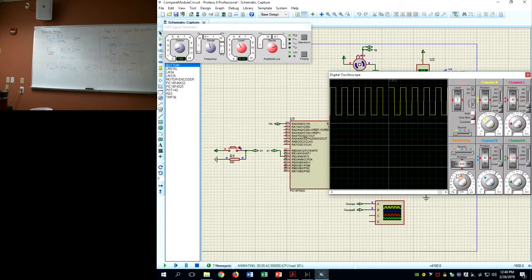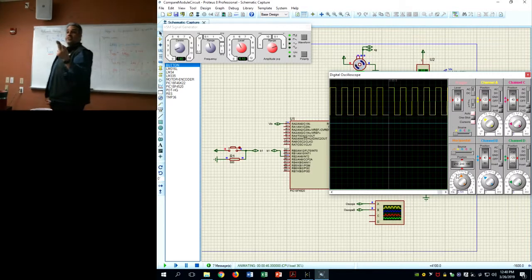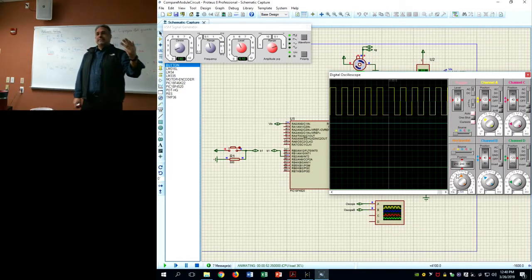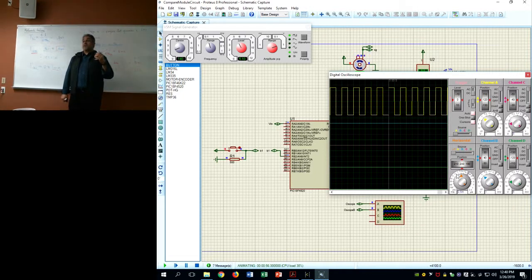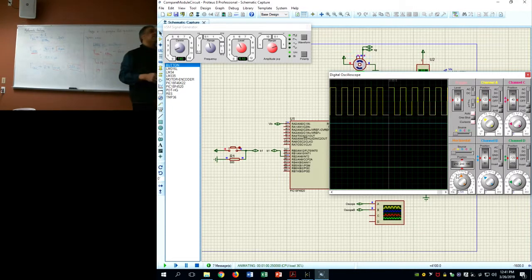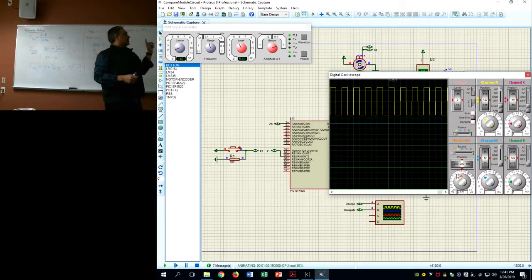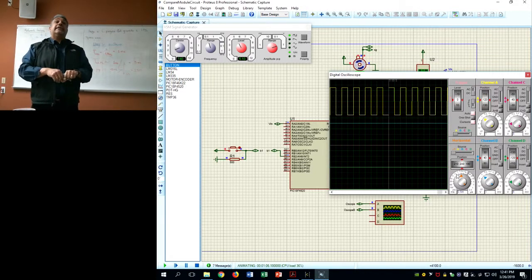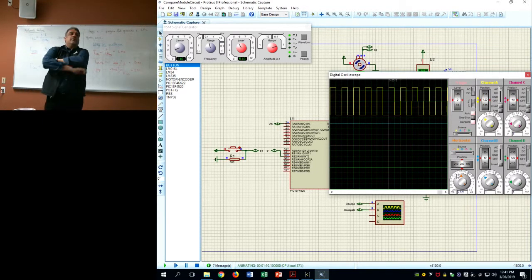You can do this for all kinds of applications. LED fading, you can do this for sound generation, beat generation at different frequencies and at different pitches. This is actually used for gaseous medicine delivery. This is used for making sure that we have countdowns. So if you have a specific event and you want to count down from 1 spot to 0 and then create an interrupt on that, that's how you do it. So this compare mode is the most versatile counter that you can find inside of your microprocessor. And so these compare modes are used a lot.